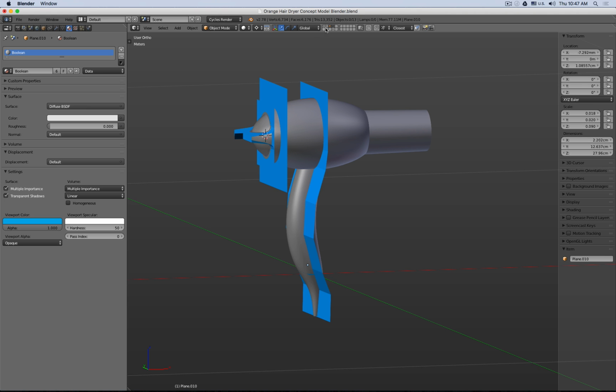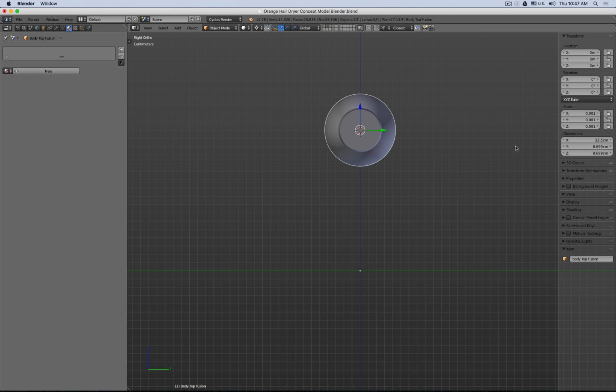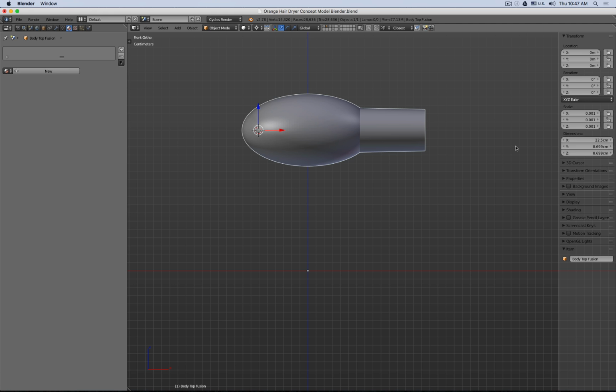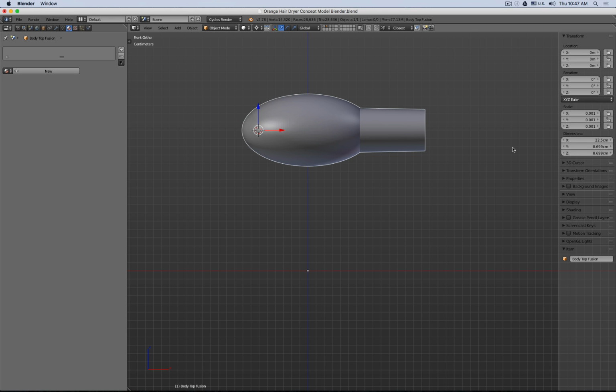In Blender, I imported that STL mesh. You see I adjusted the dimensions from meter to millimeters, and then Blender converted it automatically to centimeters. So my object nicely snaps into the same position where it is in Fusion. Perfect.